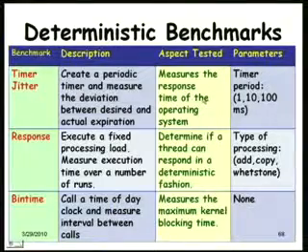Here it measures the response time of the operating system. Basically, the timer will report the event, right. It is not that the timer did not work, the timer has reported the event, but it is the operating system which has taken time to respond, or it has taken a different amount of time each time the timer has given an interrupt.